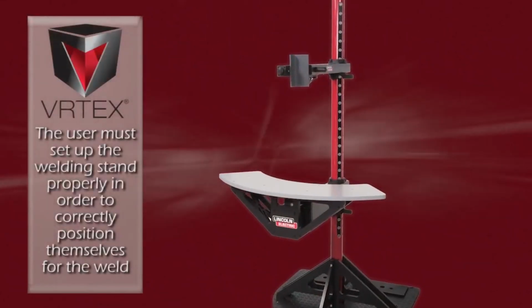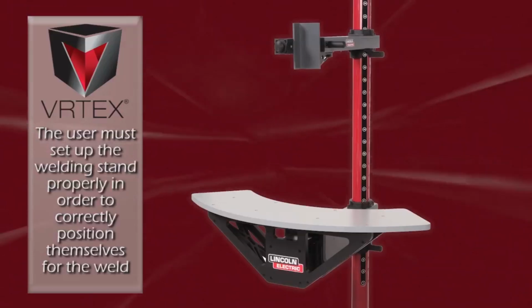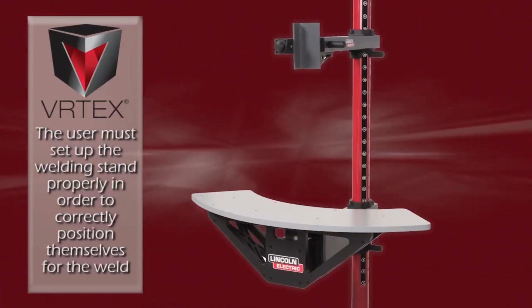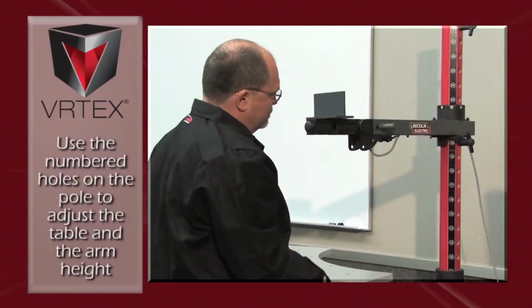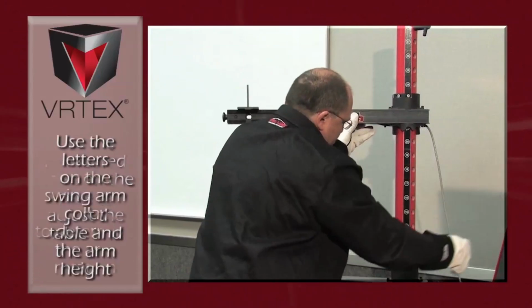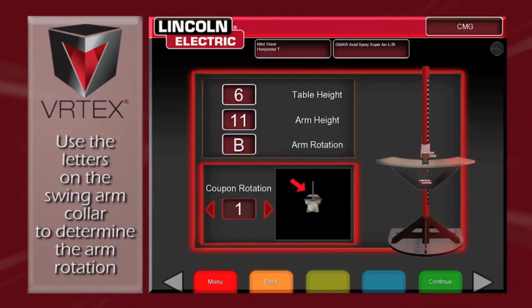Setting up the welding stand is very important. The user must properly set up the stand to figure out how to position their body so the weld can be made without stopping. Use the numbered holes on the pole to adjust the table and arm height. Use the letters on top of the swing arm collar to decide the arm rotation. The coupon rotation will depend on how the coupon is set in the arm.